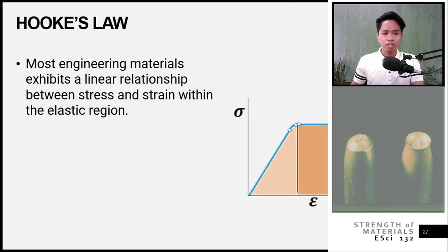In this region, based on the figure, the maximum limit is called our proportionality limit. As I said before, for steel, the proportionality limit, elastic limit and yield point are usually found close together, so it is hard to detect.